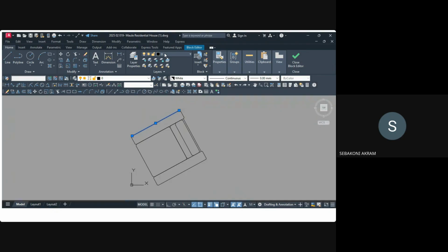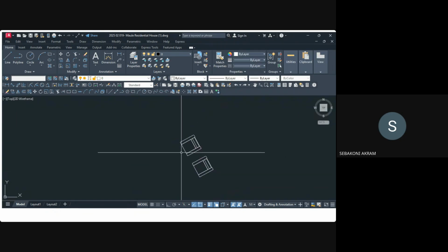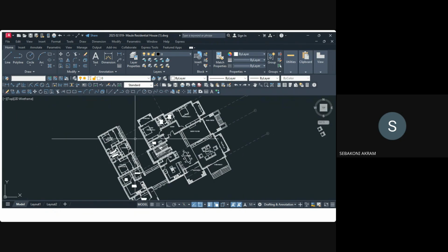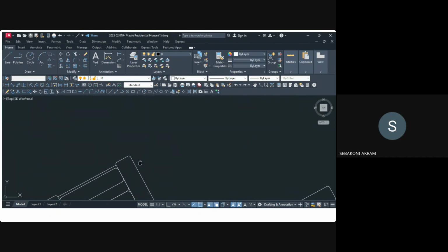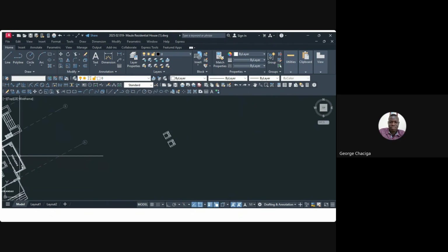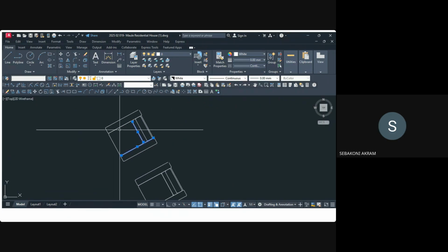Are we together? So that's the importance of exploding this DWG before purging or deleting any other layer, because I want each particle. If I explode now this, if I highlight it and I explode it, now I can select each particle. Are you seeing, this block here? I can select its particle.